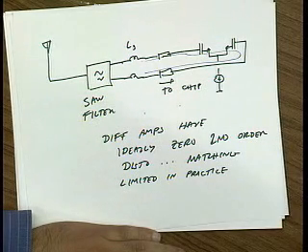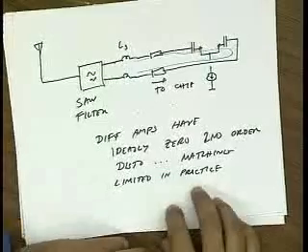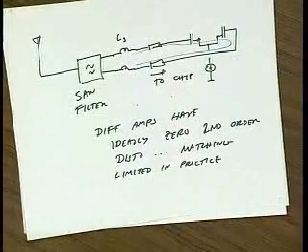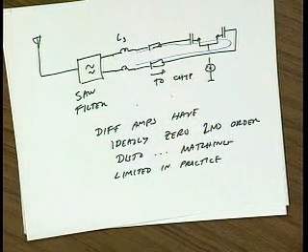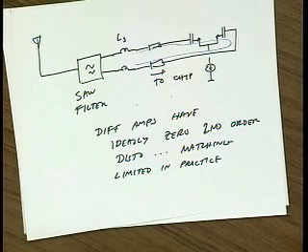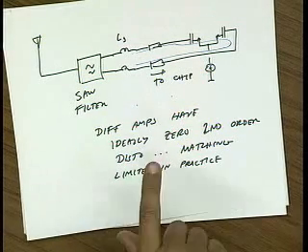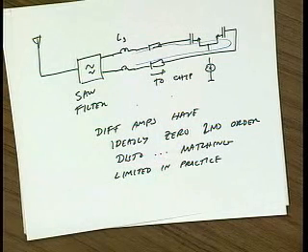Yeah, in a bipolar design, if you're at a frequency, let's say FT over 10, and your beta is reasonable, let's say about 100, the input impedance is more or less capacitive, 10 times more capacitive than resistive. Okay? So the beta roll-off, right, is beta times lower than the FT frequency. So you can see that the real component starts going away very quickly. So effectively, if you're using a bipolar transistor, let's say FT over 10, forget the real part. It's not going to make a contribution.